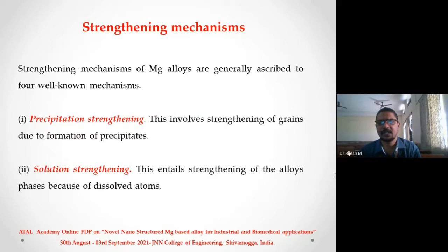So that's one of the reasons why most of the alloys are stronger than the pure metal. When I say stronger than the pure metal, I always mean that they're not as ductile as the pure metal. Sometimes if you add more than one alloying addition, they may form intermediate precipitates. These precipitates can be in nanostructure. You can engineer these precipitates, and you can go for a process called precipitation hardening or age hardening, where you engineer these precipitates in such a way that they'll block the dislocations when plastic deformation is going on, and then improve the strength.